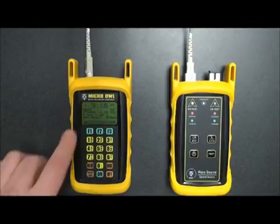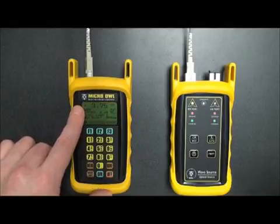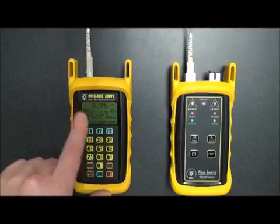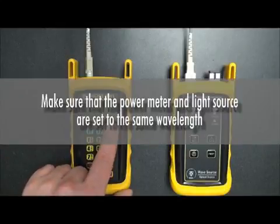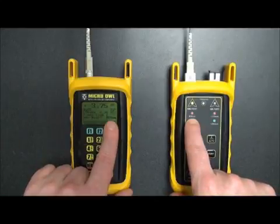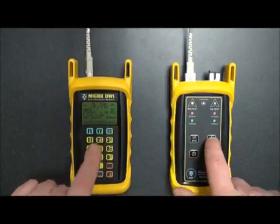Now, as you can see, we see a reading up here. Doesn't look right. We're supposed to have zeroed our equipment. Now, the reason this reading is incorrect is because our wavelengths are not matching. As you can see, it says 850 nanometers here, but our light source is set to 1300. So what we need to do is set our wavelength to 850 nanometers.